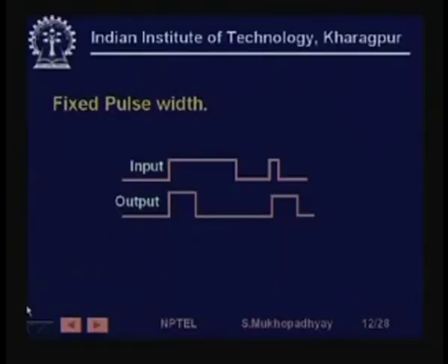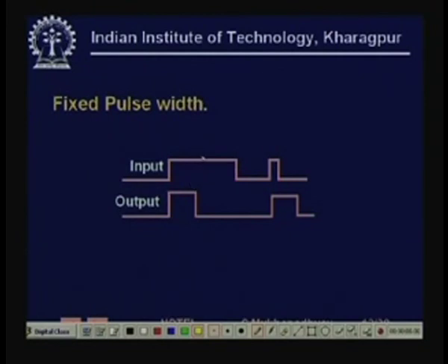Every time the input goes high, the output immediately goes high, and irrespective of the input, it stays for only a fixed time and then comes down.